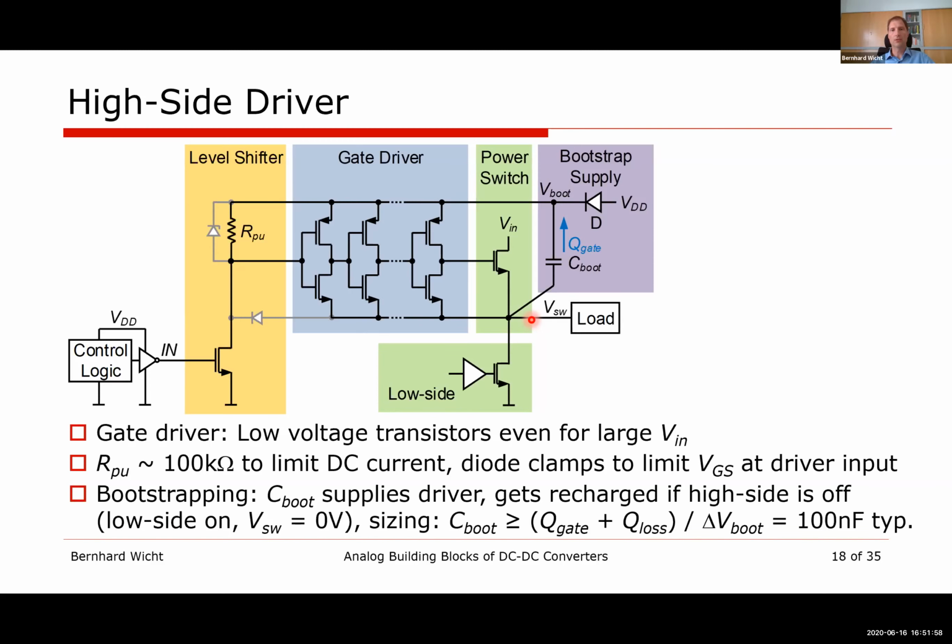Yes, actually, it's two things. It's stability issues, and the ringing that we get can also exceed the maximum ratings of the power stage. Usually these transistors are rated much higher than the V-in level. In a discrete power stage, there is a factor of 3 at least, to leave headroom for ringing so that the transistor doesn't get destroyed.